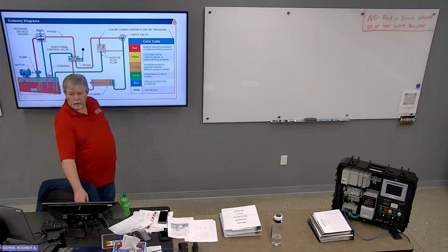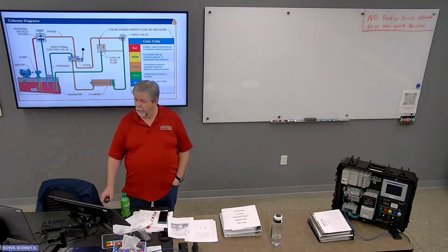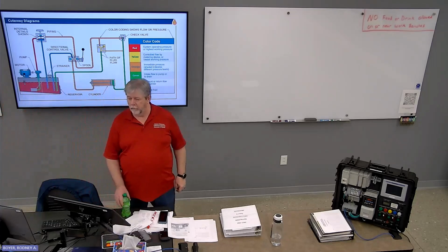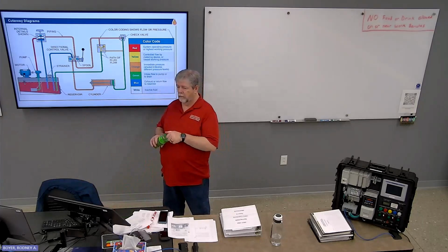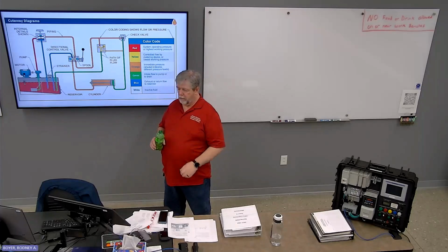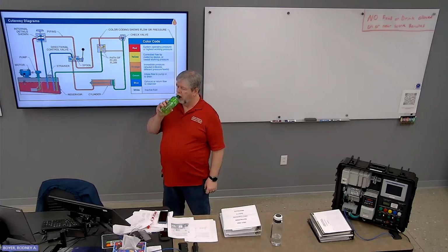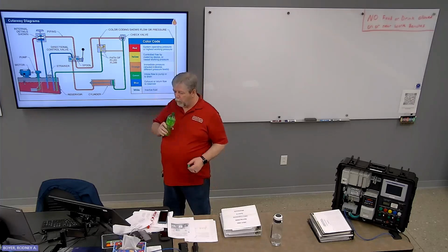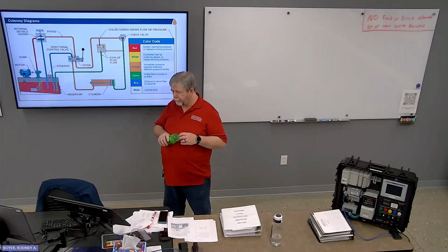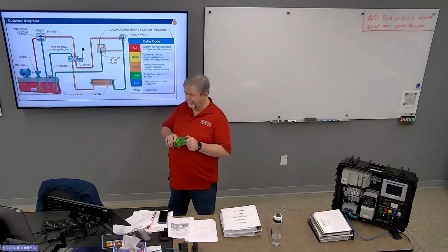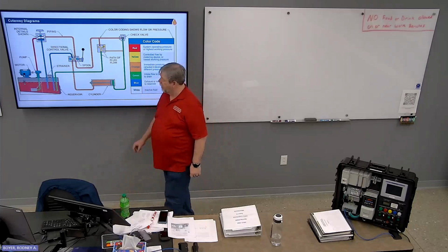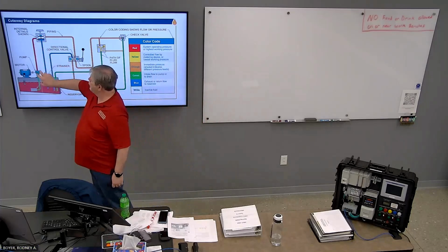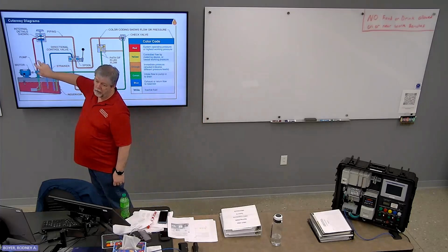So Rod, I have a question, just to help me understand this. If this were an electrical diagram, this would be wired in series, and that's why we're kind of losing pressure throughout. And for it to be wired in parallel, we would need another motor at the reservoir, basically another source line. You would need another motor, but another line from source. You'd have two parallel lines coming out here. Gotcha.